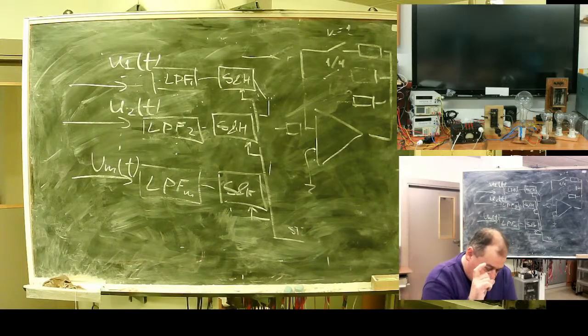Some designers do isolated ground for this part to prevent infiltration of power supply pulses, power supply noises into this analog part.